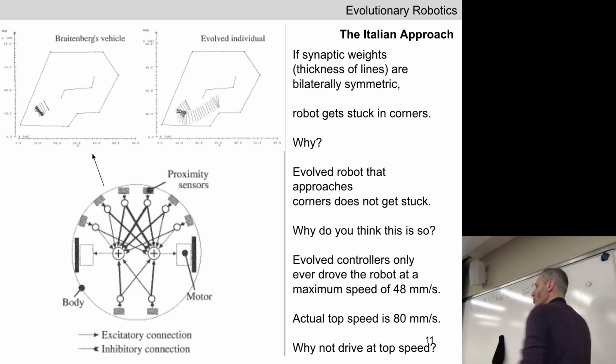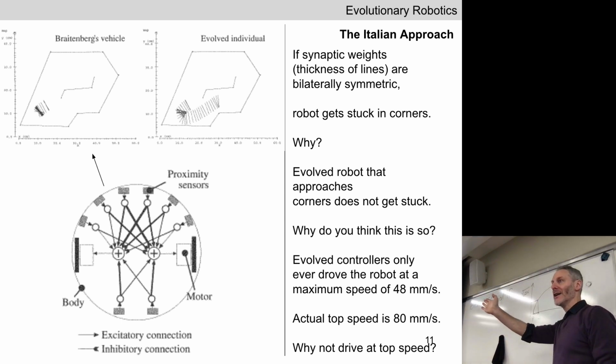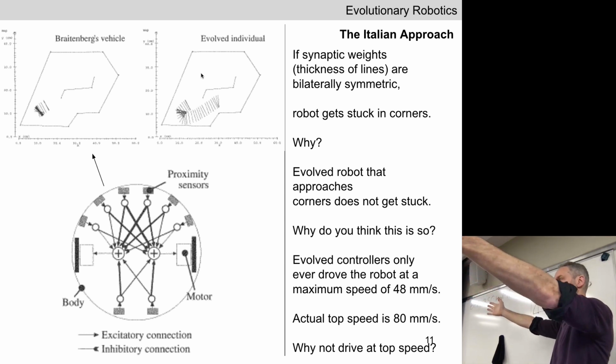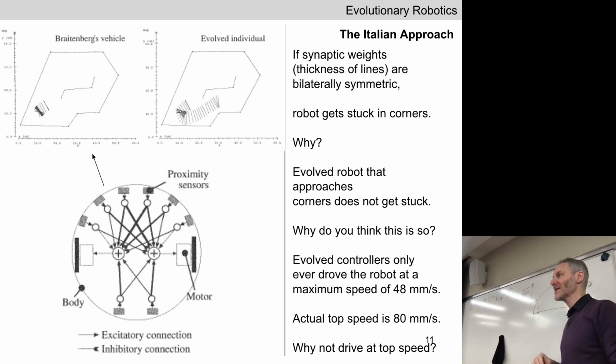The robot should turn to its right, away from that obstacle on its front left. And hopefully if it points up and into the tunnel, into the track, there's less stimulation of the 6 proximity sensors on the front, and it goes forward. That was the best they could come up with. And it does okay at driving around and around the track, but the Braitenberg vehicle has a problem.